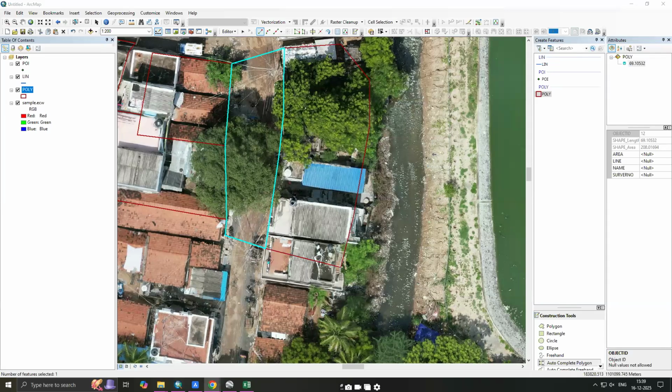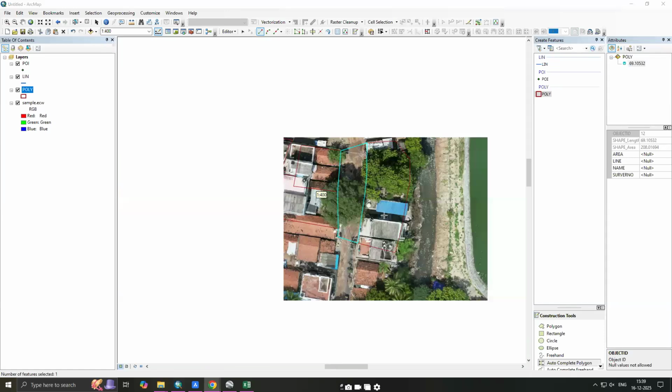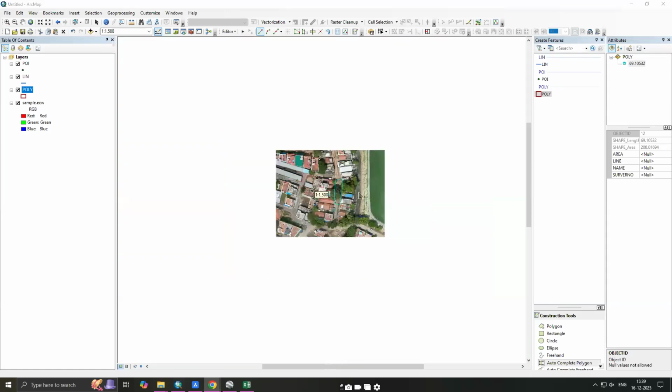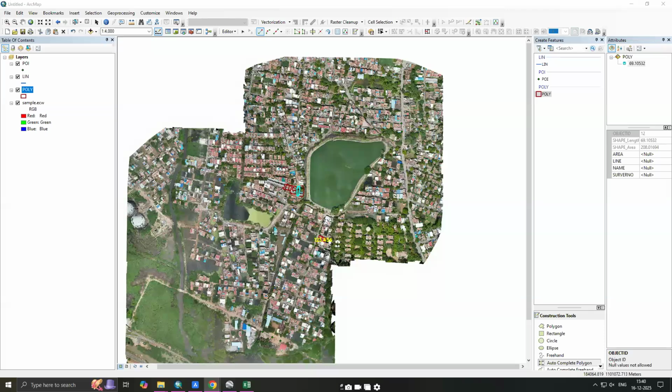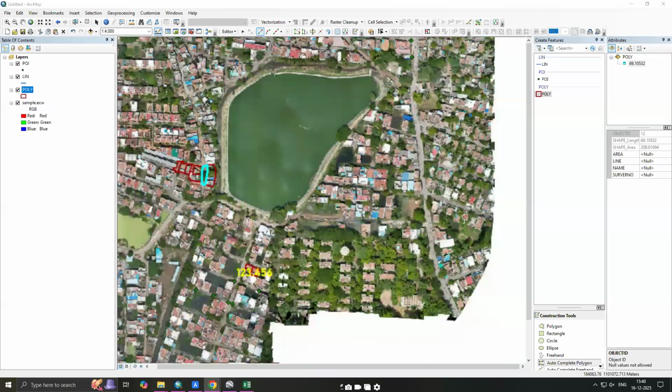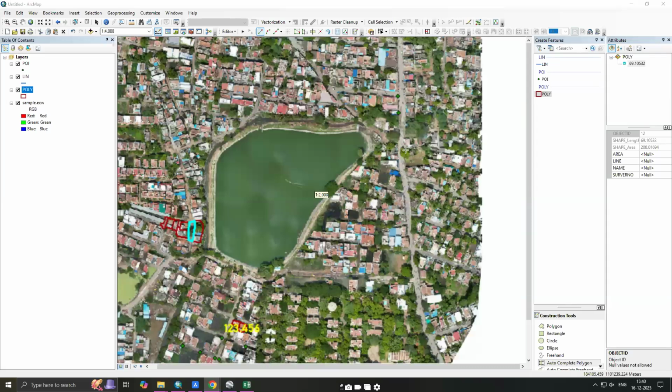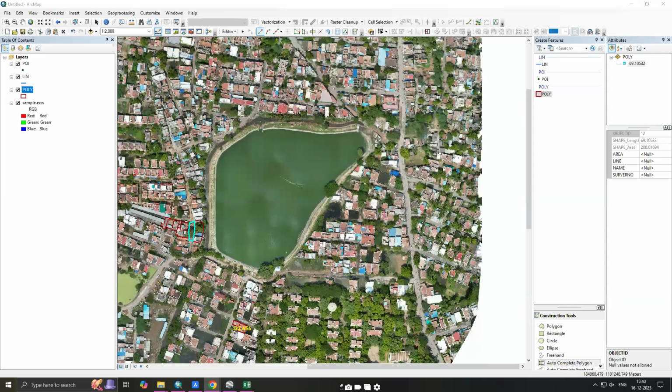Because once you have more buildings, correct? In this photo, if you are considering like this, it is always road which is more. There might be some 10,000 villages, but all 10,000 villages are connected to roads, which means the quantity of road is more as compared to buildings. So it is better to start with road, irrespective of the hierarchy or number of quantity. You start with road because your road will have connectivity to all features.